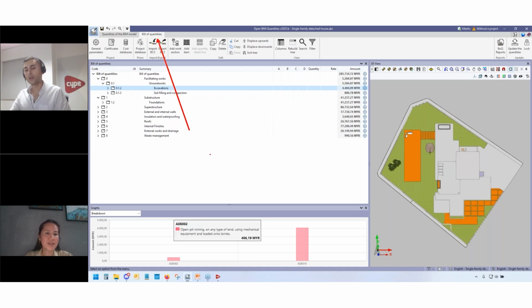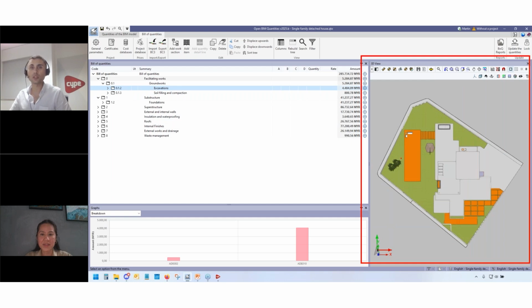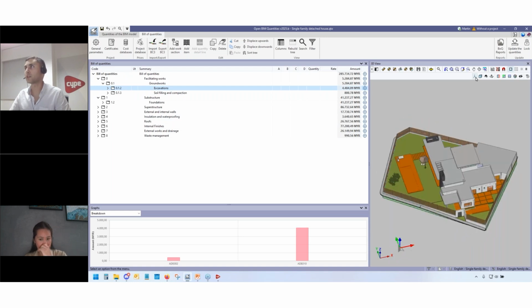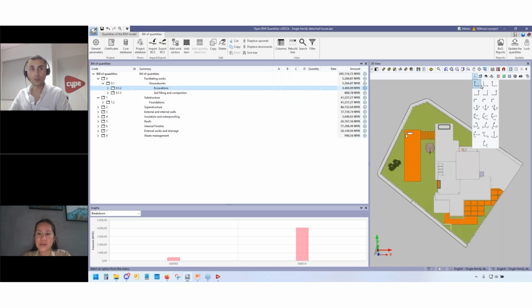We're in the bill of quantities tab. And in this 3D view panel, instead of reading a BIM model from BIMserver.center, what we should do is open an empty file and load by using these 3 commands over there, the DXF, DWG tools. We may load plans in the DXF format, for example, or DWG, or PDF, even image files. We would import that and see this as a 2D image. We're seeing a 2D image now, but it's a 3D model over here, right? But we would see this as a regular plan like we've been doing for decades. And we could use these powerful tools over here to manually measure in a really productive way the 2D. So we have this other option too, but we focus this presentation on the BIM possibilities because it's actually really interesting.